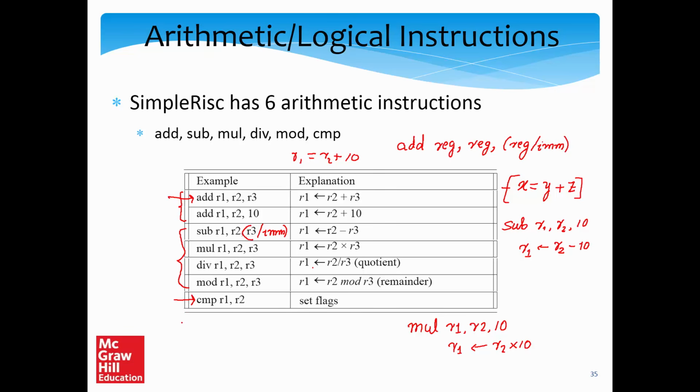We typically don't write compare instructions of this type in a high-level language. So in this case, what we do is that we pretty much subtract R1 minus R2. If the result is equal to 0, then we can infer an equality. So we set flags.E, which is the equality flag, to 1.